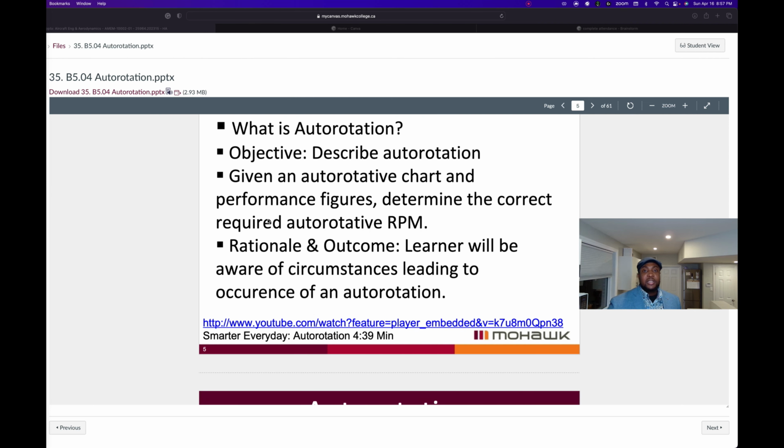The damper is attached to the aft portion or the trailing edge of the root of the blade, and you can see that the lead lag hinge, or drag hinge, or vertical hinge, whatever terminology suits you better, is what allows that blade to move forward. The damper basically prevents excessive movement by allowing a fluid to flow in a metered way through a small orifice within that container.